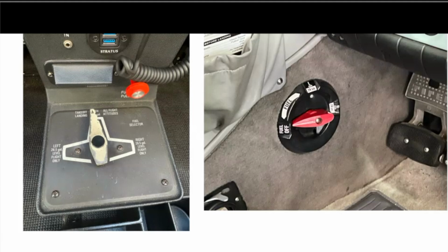But again, what are you going to do? You're going to monitor your fuel gauges. If for some reason the left tank or the right tank is empty, is it a problem? Not necessarily. That's the benefit of the high wing and the gravity fed. They're both feeding. So unless you're in some really, really funky attitude where that fuel can't get to the engine from either one of those high wing tanks, you're in pretty good shape.